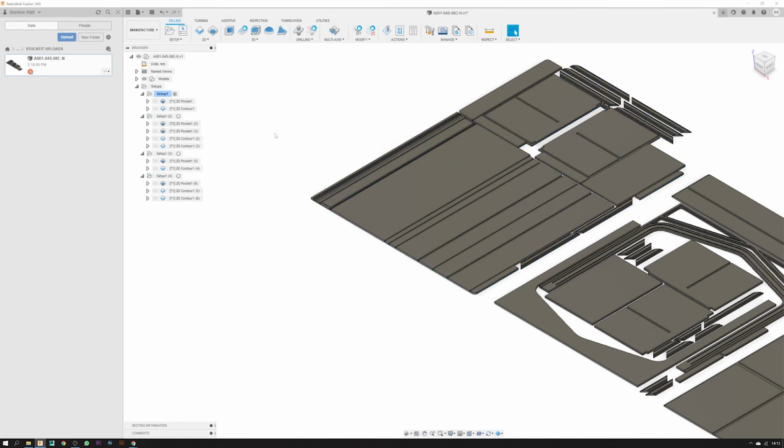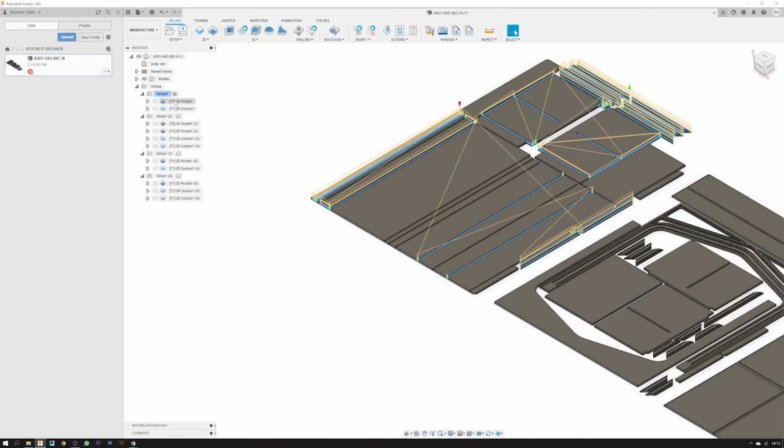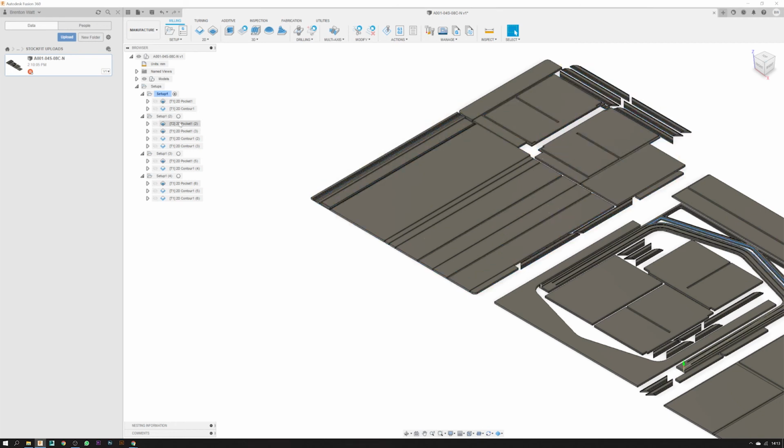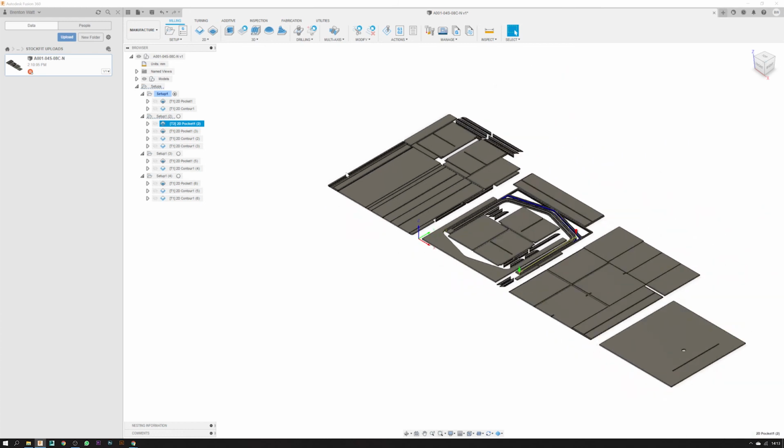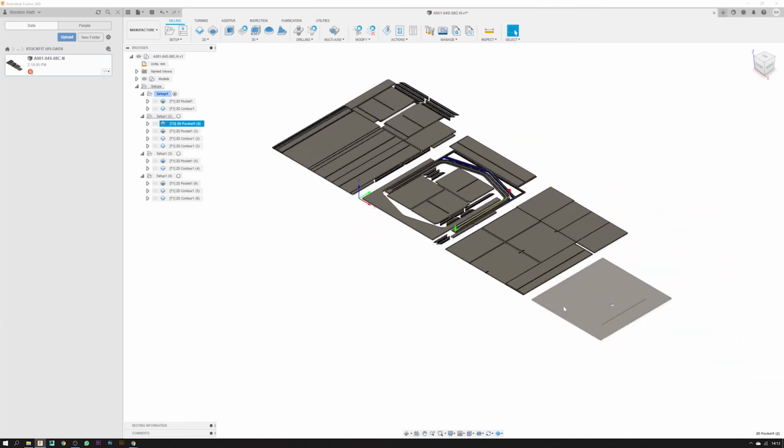You might also have a tool changing machine that can switch between tool 1 and tool 2. What we've done here is we've got the 3mm bit up as tool 2 on our machine. So in your case, if you've got a single spindle machine and you use this, even though it's tool 2, in most cases it should default to a single spindle type of thing. So keep that in mind. If you've got a tool changer, then you can obviously change all the tooling to whatever your requirement may be.